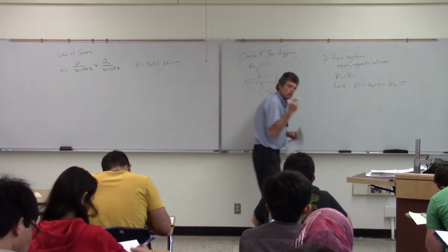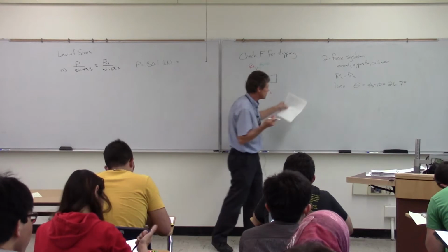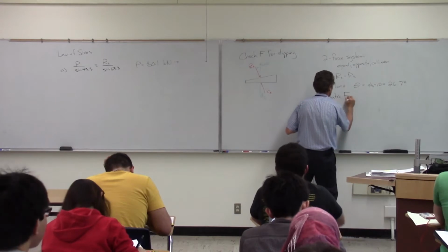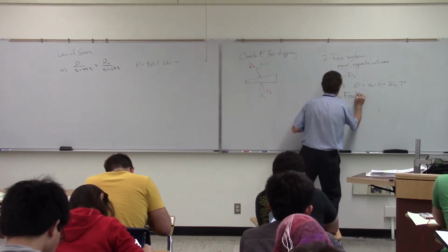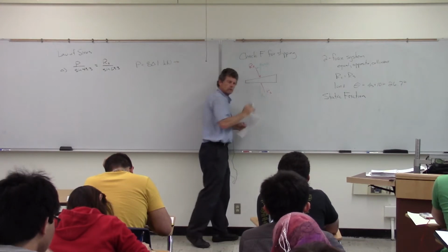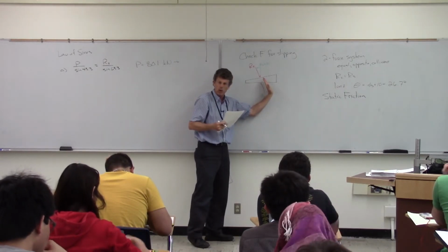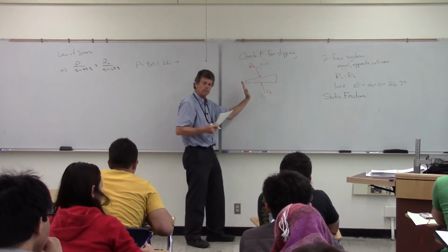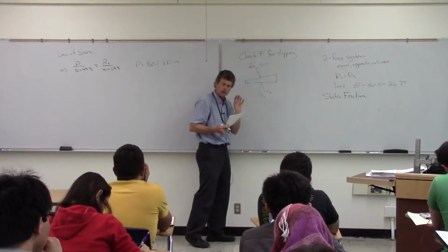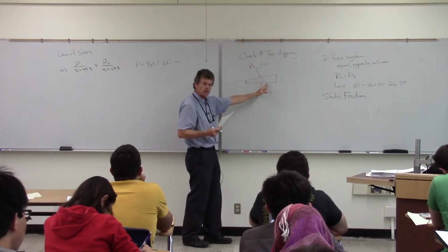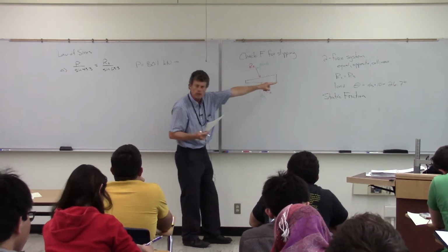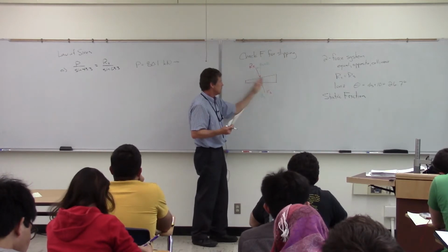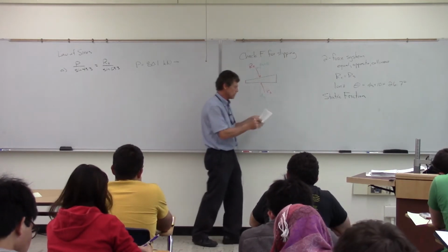Now, what we can do, though, is check that against the friction coefficient there, the base. So for static friction, if we want it to be held in place, then basically what we're saying is the reaction angle needs to be greater for it not to move. So we basically have to calculate the friction angle there, and if it's greater than the angle that we have there that's necessary for equilibrium, then basically it's not going anywhere. If the angle is less, then basically that means it's shooting out.